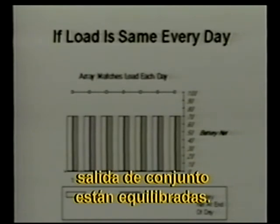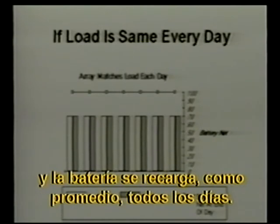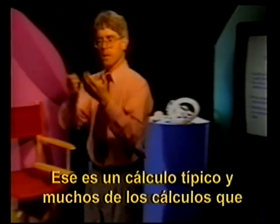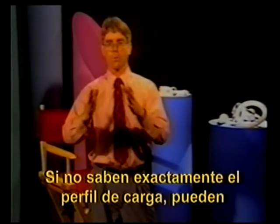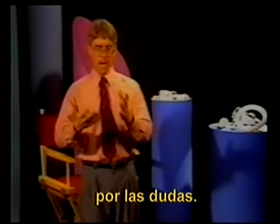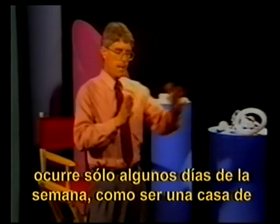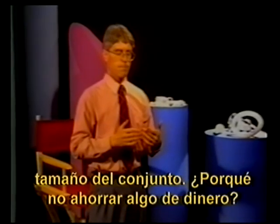In this case, the array replaces the load every single day, and the battery is recharged on the average every day. So that's a typical situation. A lot of your calculations are going to be that simple. If you don't know exactly the load profile, you might simply guess that the load is the same every day, just to be safe. But if you know for sure that your load demand is only a few days of the week, like a weekend cabin, then you can economize on your array sizing. Why not do that? Why not save some money?